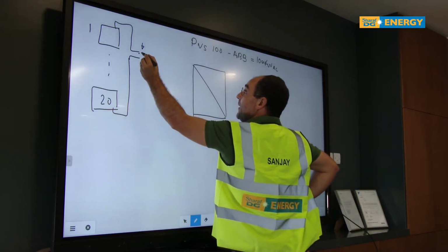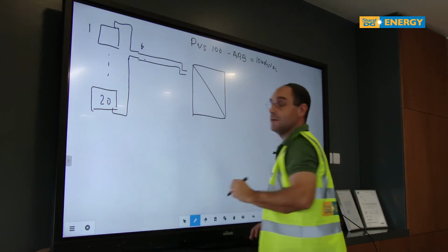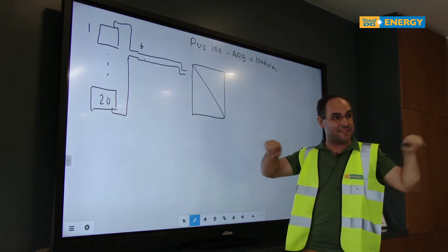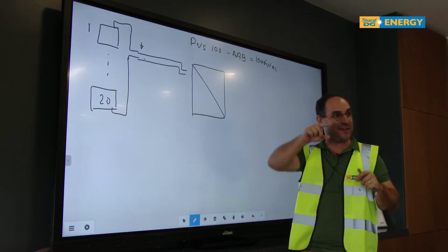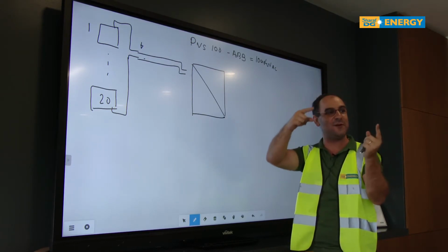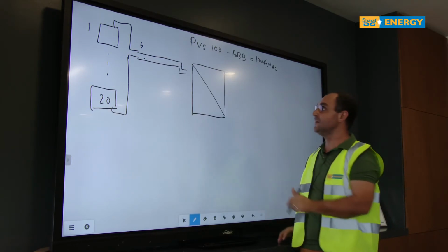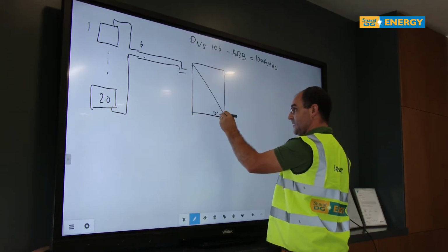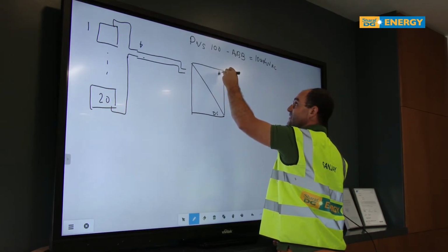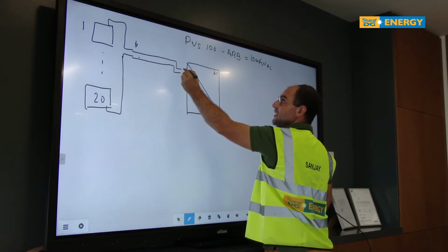So what's going to happen now? Since we build up the panels in series together on the roof and there is 1 plus and 1 minus left over, we bring this 1 plus and 1 minus up to the inverter. That's what the schematic represents here, right? The inverter has a DC side and an AC side. So the DC side comes here and we connect here.